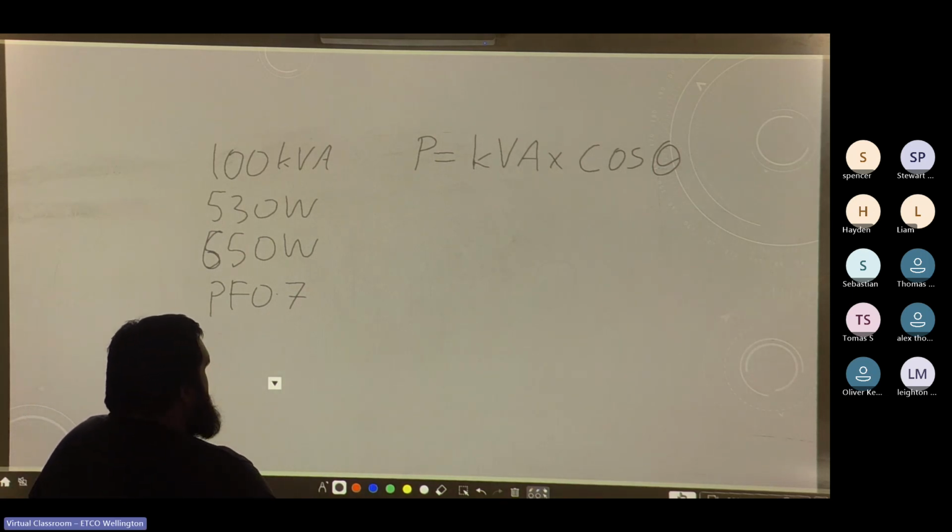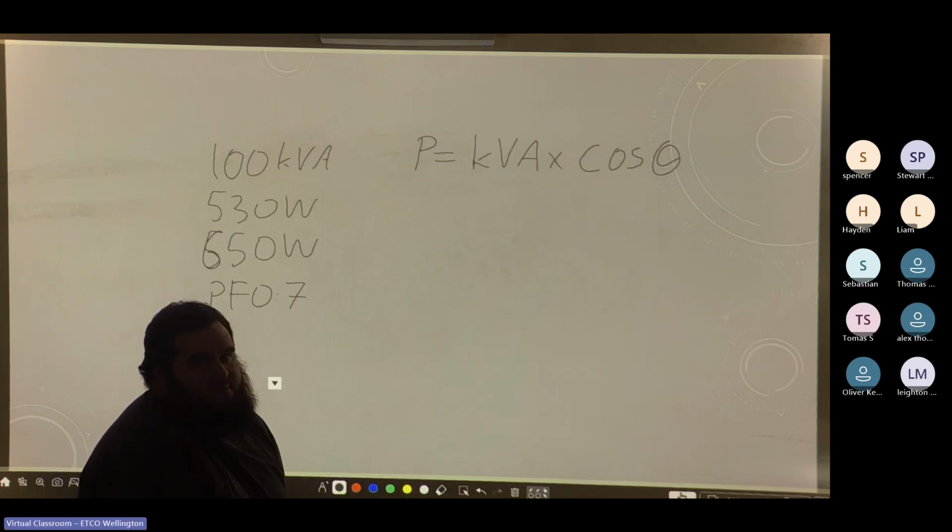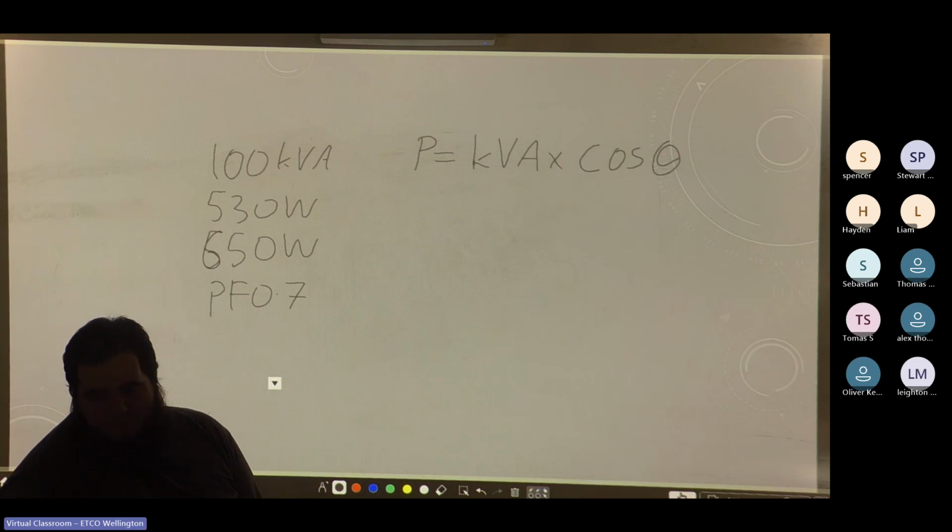So your power is equal to your kVA times your power factor. Okay? So your power, which is measured in watts, is your input in kVA times cos theta, which is your power factor.